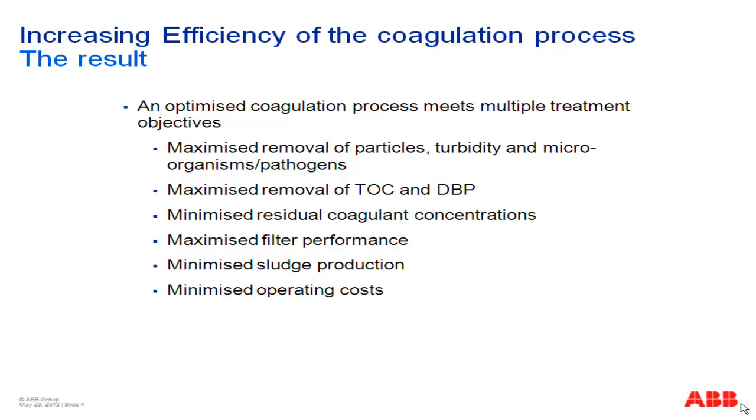I've had process scientists tell me, we sometimes will up the dose by up to 25%, 30%, even up to 40% more, just to give us a buffer when the site's unmanned in case there's any changes in conditions, and it just gives us a bit of time to get to site and hopefully sort the dose out from there. So big savings to be made in dosing coagulants.